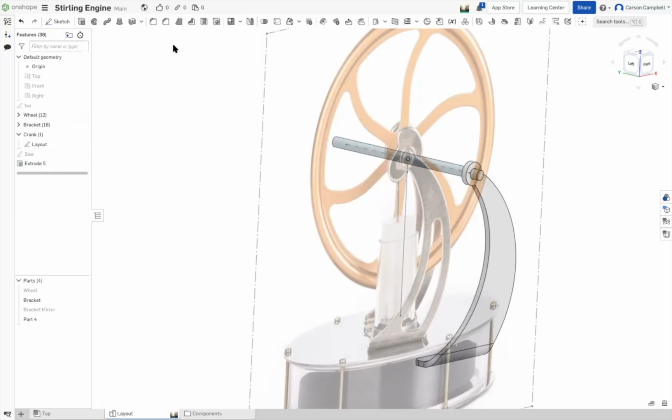One of the things that I see is if we draw one of them, we can mirror it to the other side, so it's half the work. Is that something that you would prefer to do? What would be the most efficient? Doing one side and mirroring it and then moving it. Yeah, totally. So let's go ahead and change extrude 5 to a blind, and we'll only get half the shaft.